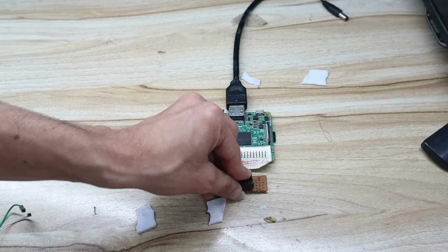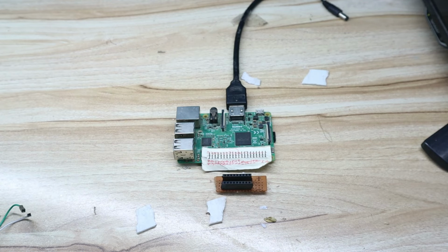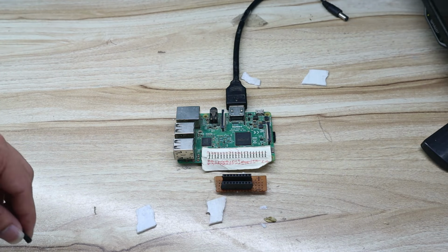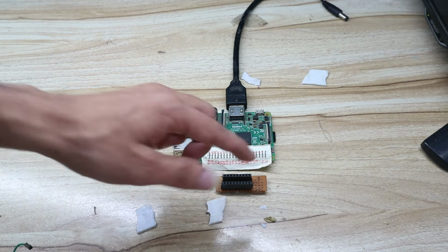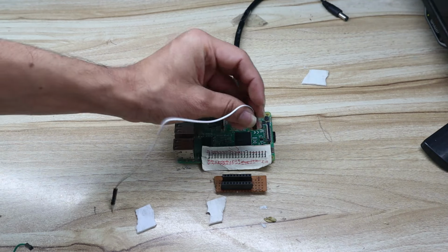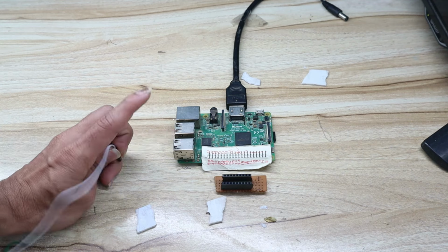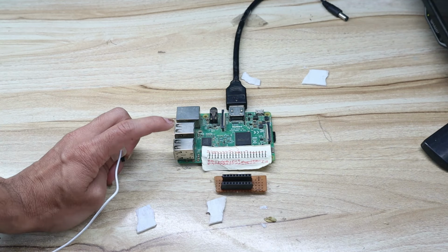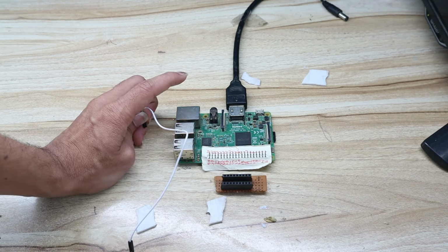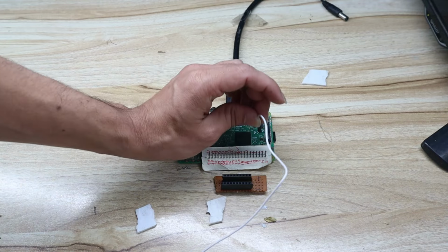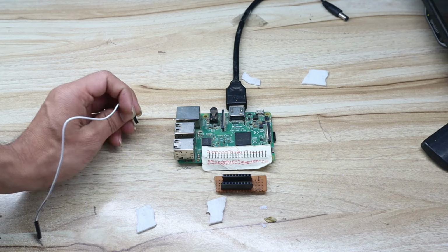Okay, so first I will place it here. Then the next pin is the power pin. The fourth number pin of Raspberry Pi is the power pin. So how to identify the pin numbers, and what is the use of the pins? You need the GPIO library in Raspberry Pi. How to install that GPIO library, I have already explained in my previous video. That summary you can see on the screen. Please install the GPIO library in your Raspberry Pi.